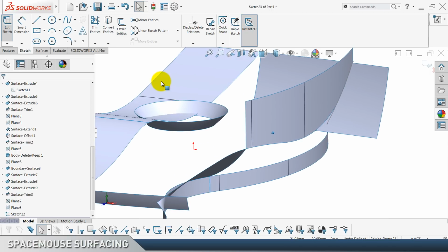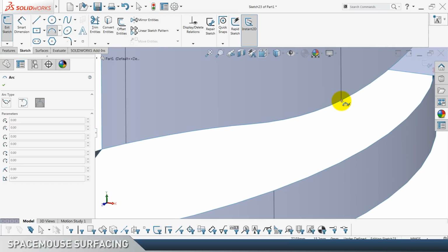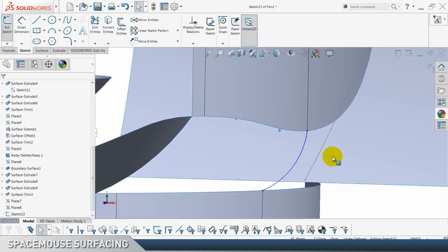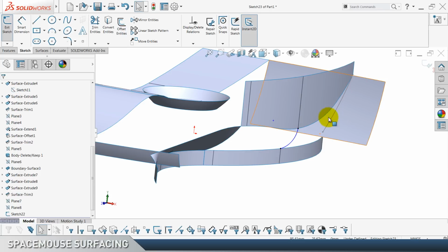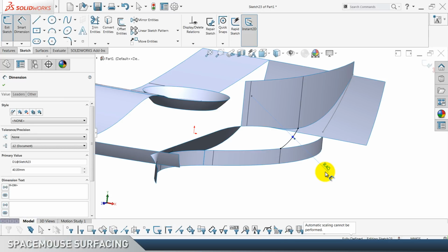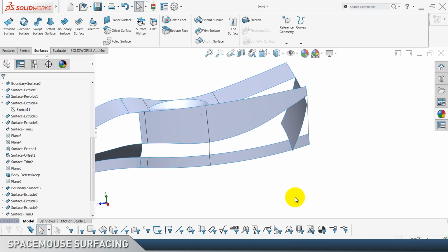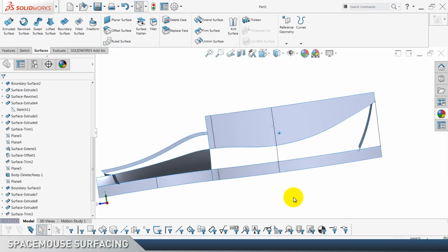And we are again drawing something similar. Let's try catch this point right away. So from this one till this one, this is the shape of the arc, same like this one, just different radius. Radius is 40. So now we have all inputs for the boundary surface that we have to build. So yeah, let's do it.